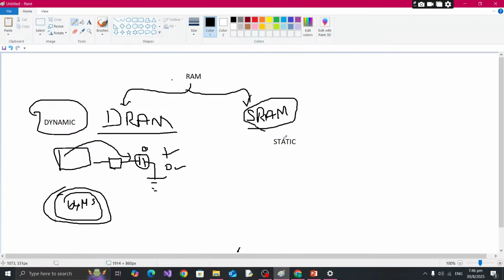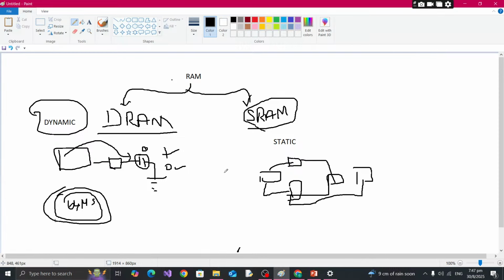But it is not the same case for static RAM. Here we have 6 transistors looped inside themselves, and it can store this 0 or 1 permanently. There is no compulsion for an extra component to read and write every 64 microseconds. So we call it static RAM.